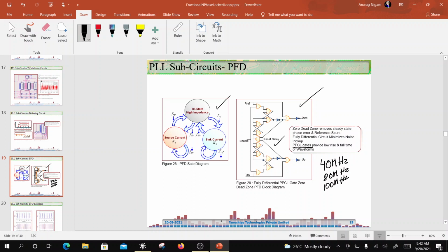So when these circuits are slower, you can make the transistors smaller. And the advantage of making smaller transistors, because they don't have to function fast, is you are going to minimize the leakage, right? So leakage is everywhere. So if you see this, everything is made up of NAND gates, right? So I am going to use NAND gates to design this, right? So this is our exercise for today.